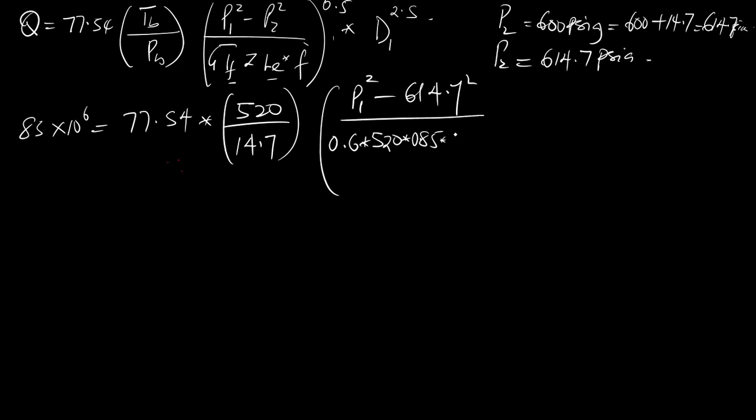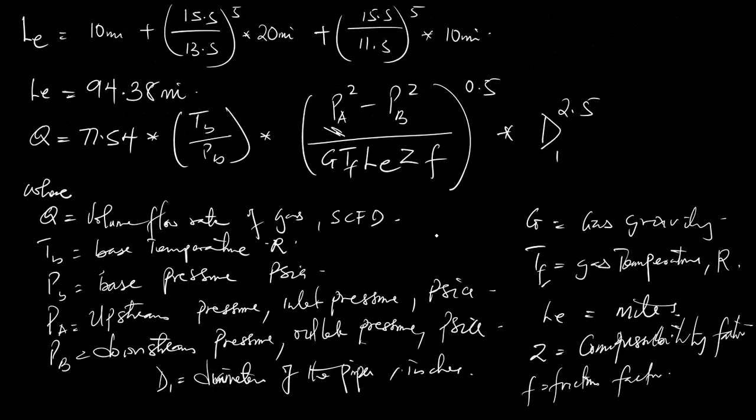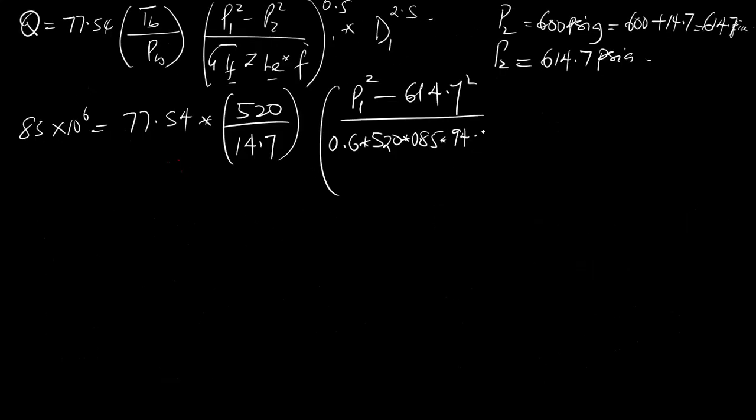The length is 94.38 times the friction factor, which is 0.015, all raised to power 0.5 times the internal diameter, which is 15.5, all raised to power 5.